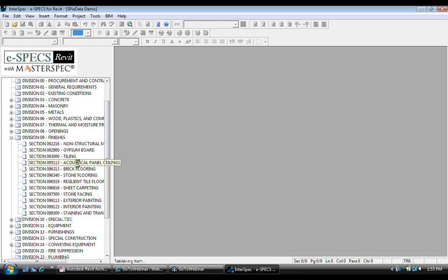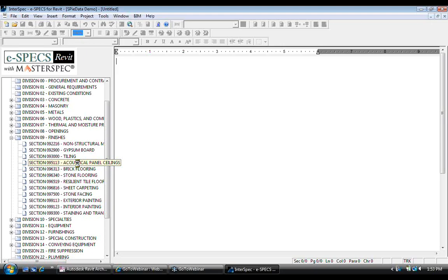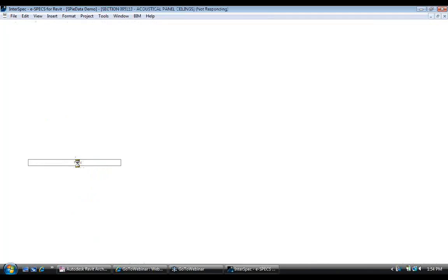The IFC model is the core exchange model for open exchange of BIM models. The SPy properties were connected to the IFC property sets, and then the work of the project was to work with the manufacturers to see what else they need to add and still keep it all connected to the IFC property sets.